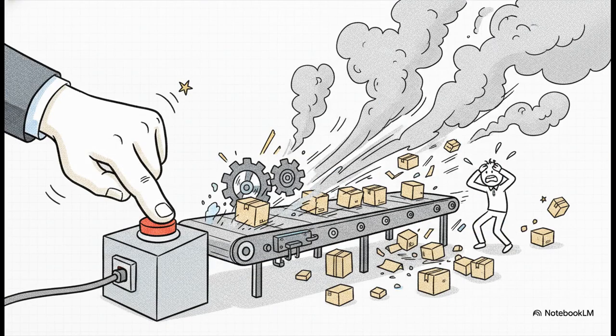Wait, before we move on, we have to talk about the engineering rationale behind a very specific piece of logic here, the AR10 one-shot. In that STL, you'll see OUT AR10 right after the shift. If you fail to include this one-shot logic constraint, you are going to cause a catastrophe. Why? Because a PLC scans its logic hundreds of times per second. So if an operator sustains a press on that IN2 button, the PLC is going to read that input as high for dozens of scan cycles.